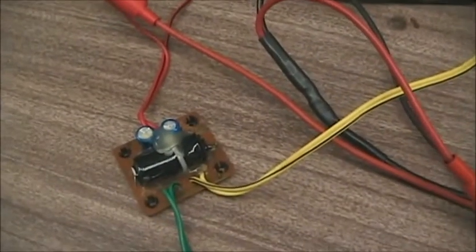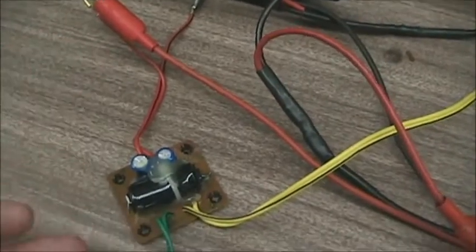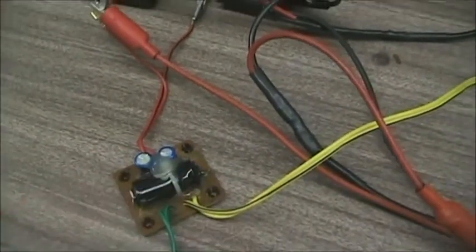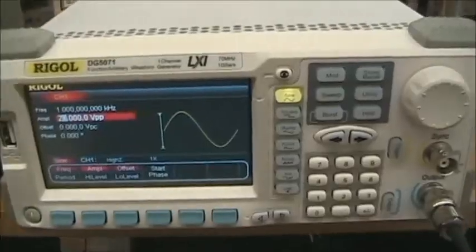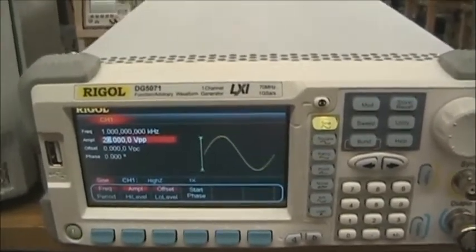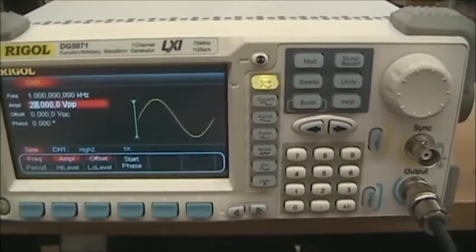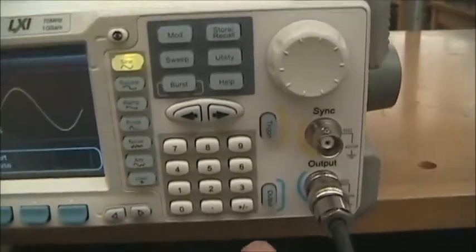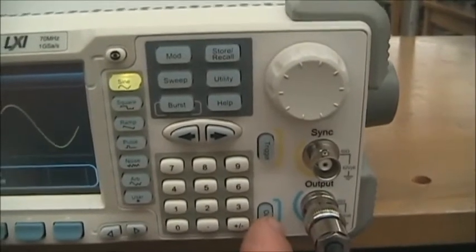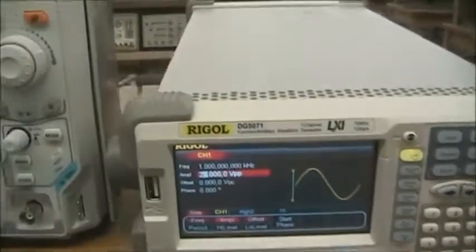Now, our network is as in the other video. The input side is the red wires, the output side are the green and yellow wires. Review that video. So one of the important features on the modern digital instruments is that you must turn on the output function for this AWG. So don't forget to do this. Press output. Now the signal will be generated.